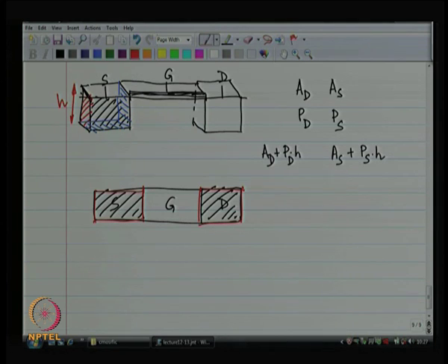Okay. So, now you know why these numbers are important when you write your SPICE net list: A d, A s, P d and P s. I am sure you have done this, right, and I do not know if you have wondered why these numbers are important. This is why: they determine the junction capacitance between the source and body and between the drain and body, right.